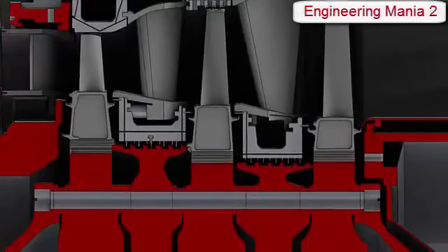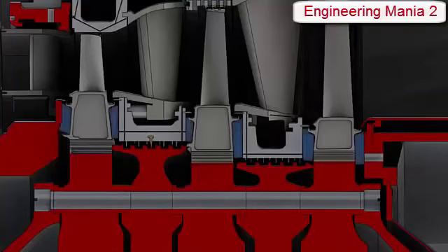All these seals reduce leakage of the hot gases radially inward to rotor parts, improving turbine efficiency and protecting the rotor parts. The rotor parts are cooled by a positive flow of cooling air discharged radially outward through a space between the turbine wheels and the turbine stator parts.